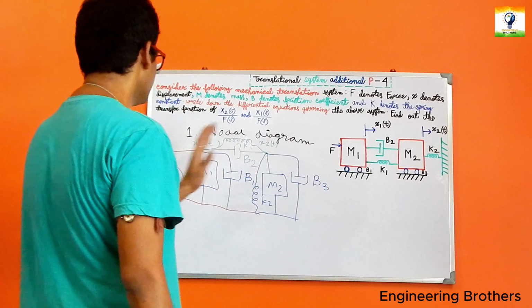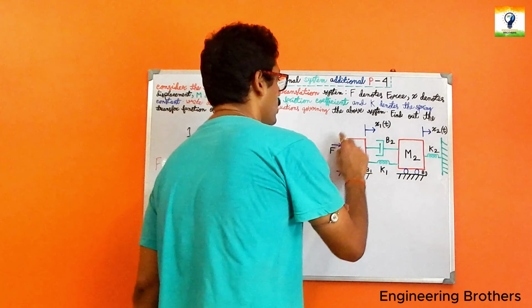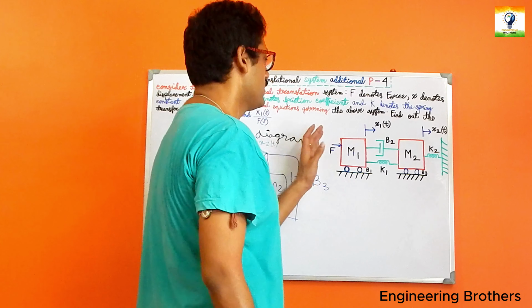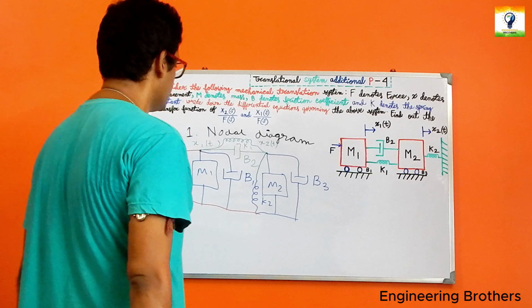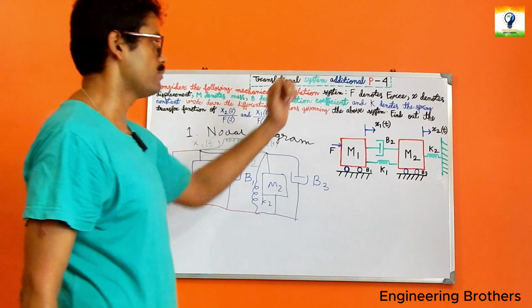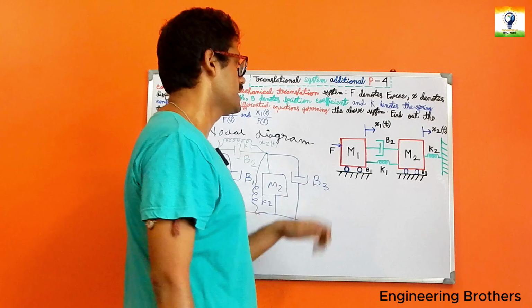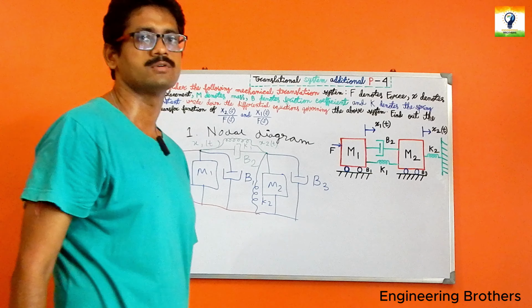And at the extreme hand side over here, we have applied the force on this block of M1. Because of that applied force, we have the disturbance for our overall setup over here. So we do require to include the force at the displacement block of our x1t, because you can see that this block is directly associated with our x1t over here.